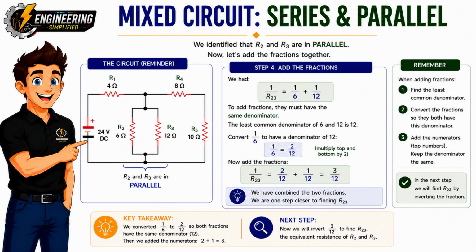Now let's substitute the resistor values into our parallel resistance formula. We've already identified that R2 is 6 ohms and R3 is 12 ohms. Starting with the formula, 1 over R23 equals 1 over R2 plus 1 over R3. Now replace the resistor symbols with their actual values. That gives us 1 over R23 equals 1 over 6 plus 1 over 12. At this stage, we're not solving the equation yet. We're simply inserting the known resistor values into the formula. Notice that we're adding two fractions. Before we can do that, they must have the same denominator, or bottom number.